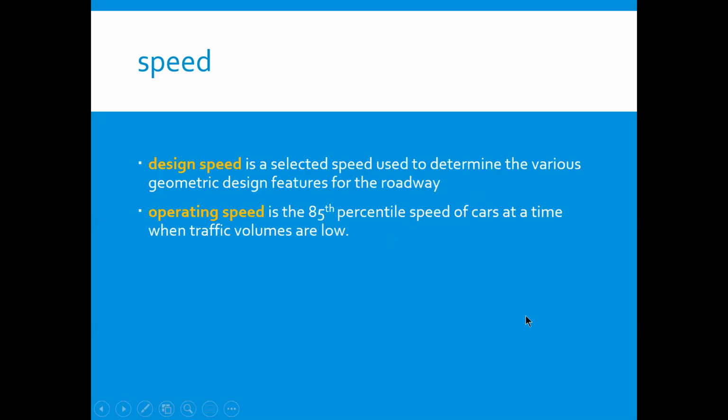The next design input is speed. For geometric design purposes, it is usual to select a design speed. It is a maximum speed that can safely be maintained over a specified section of the major urban roads when conditions are such that the design features of the road govern.